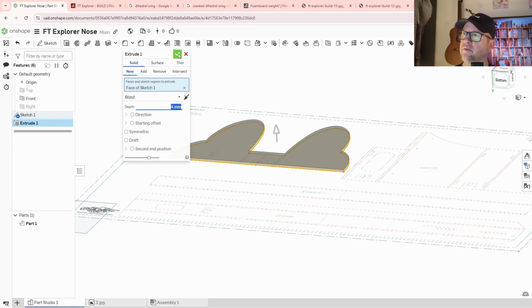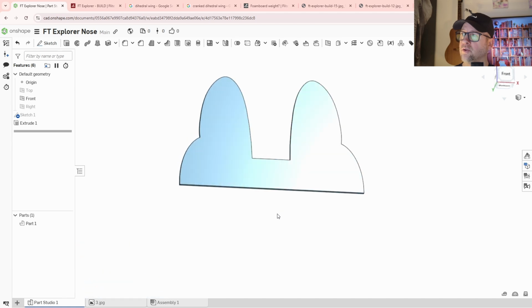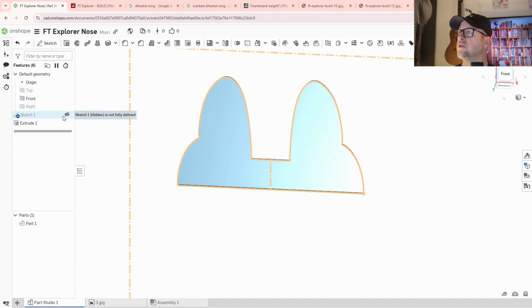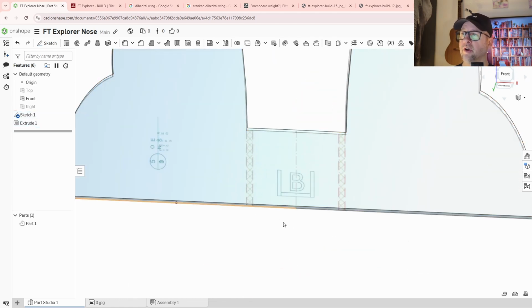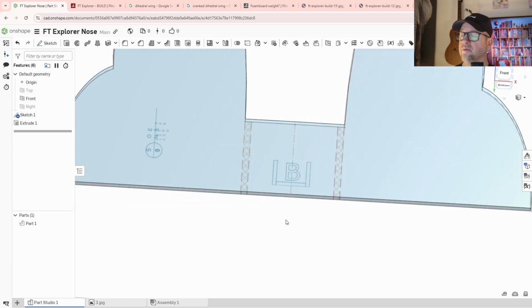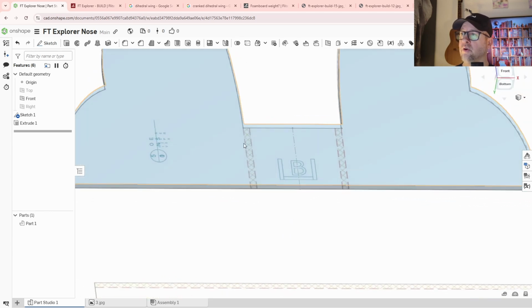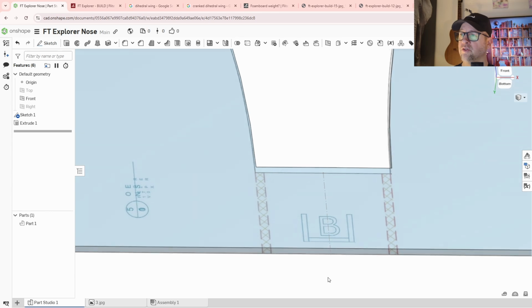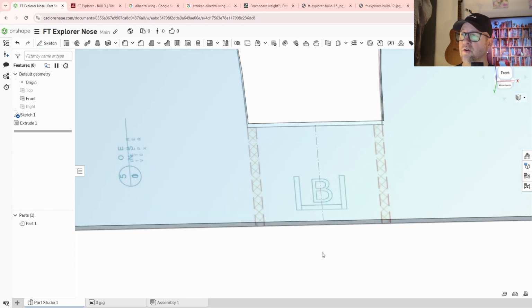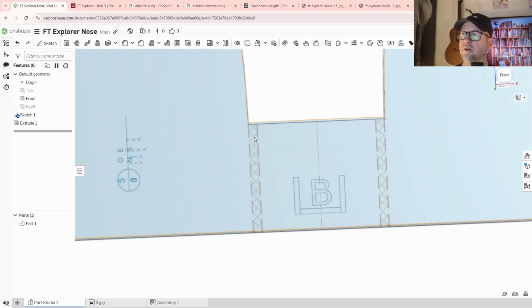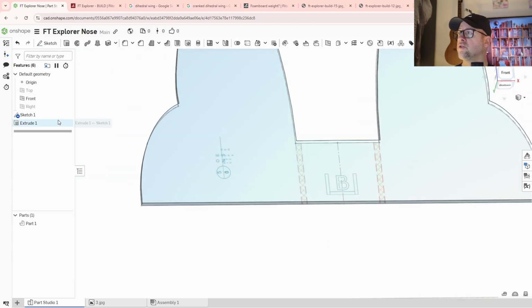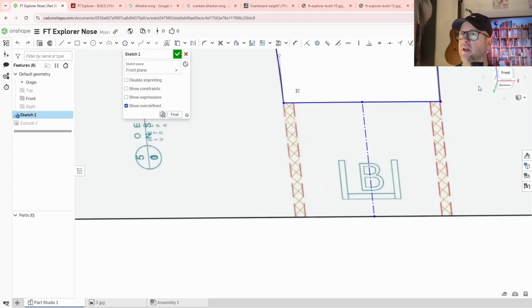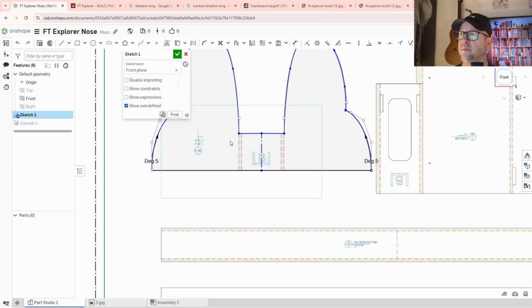I can fold it. Okay, so I'm going to get back in that sketch, or show my sketch. Where's my sketch at? Show me, there we go. All right, I had to click on the little eyeball. So I want to do a cut right here, and I can actually probably create, we could do a cut right in the middle of that guy right there. So we're going to create a construction line and then chop this. Let's create a line. Let's go back to my sketch, and then front view. Get us nice and back into position.